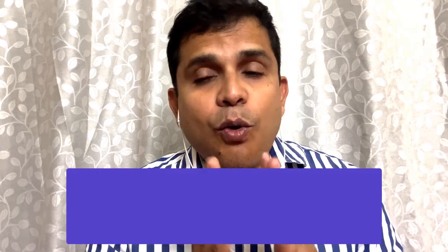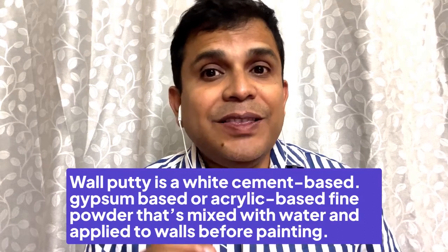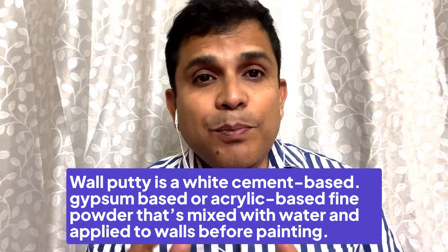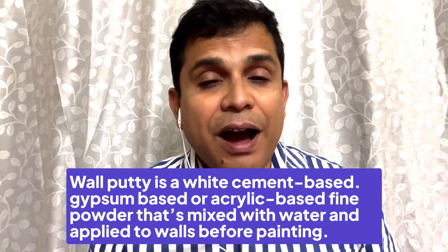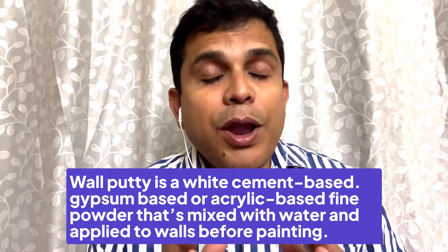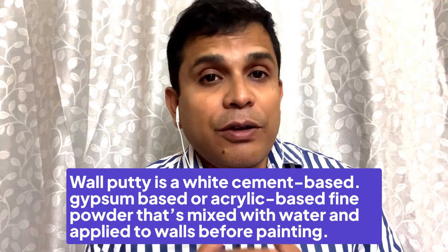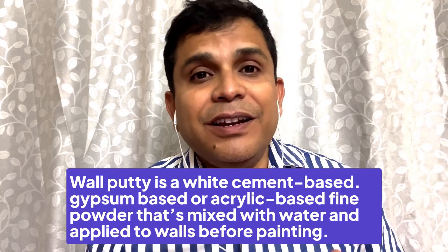Now, what is wall putty? Wall putty is a white cement based, gypsum based or acrylic based fine powder that's mixed with water and applied on walls before painting. Now, why with it? The wall is mainly a plastered surface. So on the plastered surface, there may be pinholes, blowholes and unevenness. Now, if we directly apply paint on that surface, the aesthetic view or the architectural finish will not be as per the requirement. For that, we need to make a base coat. Either it is POP, or it is putty, or something else. But in today's video, I will discuss only the wall putty. So it's a base coat before the painting.